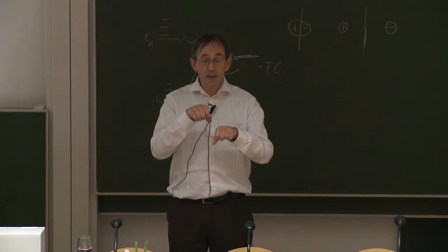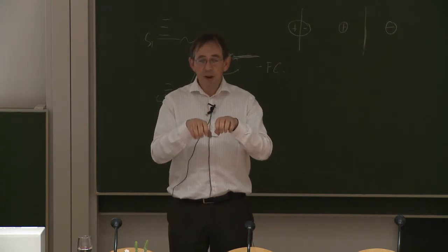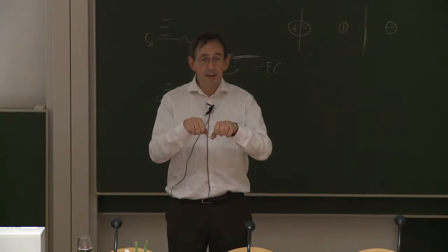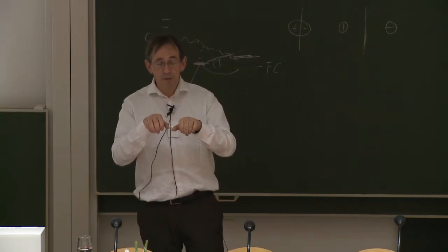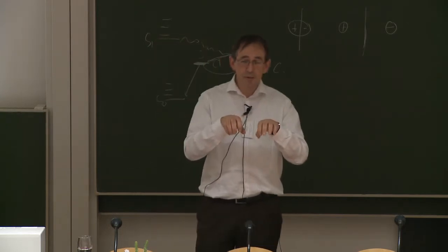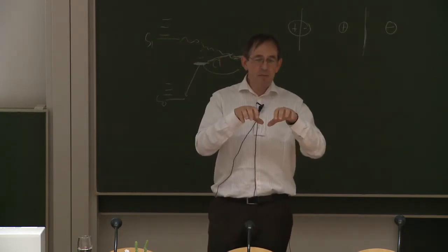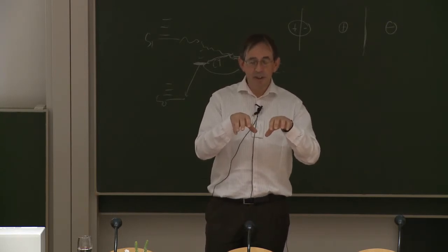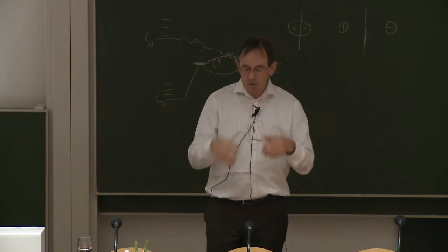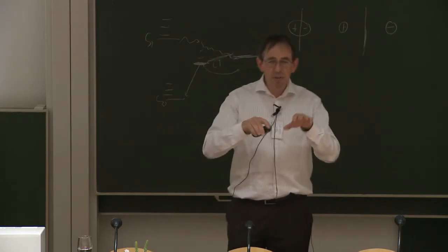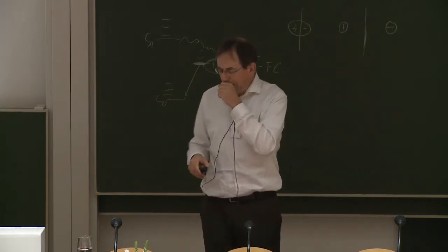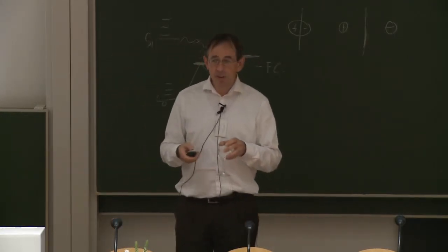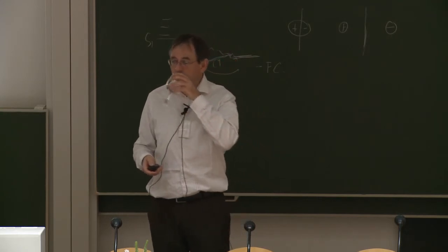So to make it work properly, you have to more or less balance the currents. Not exactly. That is something that we found out later, that this balancing of currents is nice for inorganic solar cells, but not the prime design criterion for organic solar cells. It is slightly more sophisticated there. But in first approach, it is the idea to make both cells work in concert such that they help each other as much as possible in making a high efficiency.